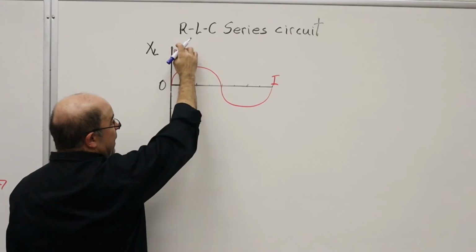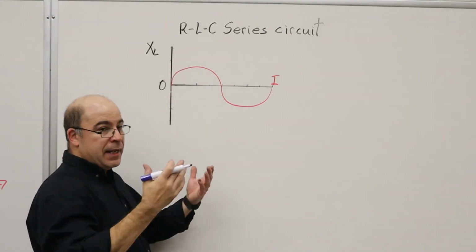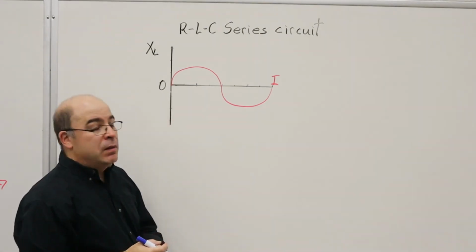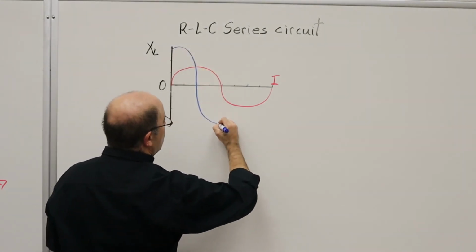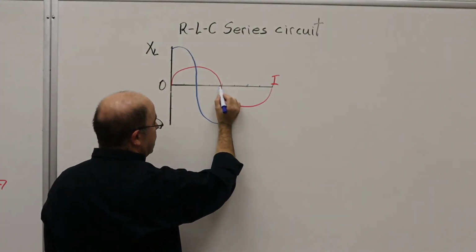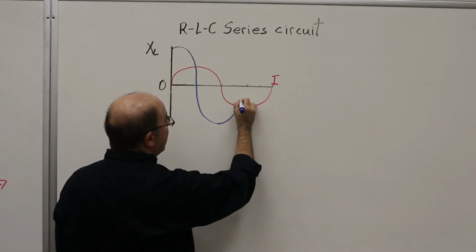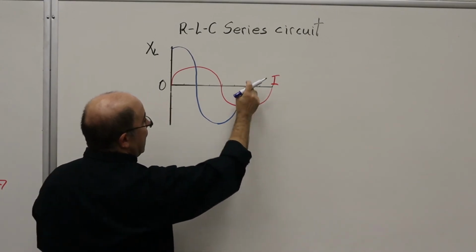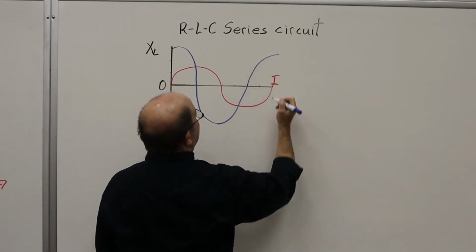Now, I'm exaggerating the amplitude because of the fact we are on film and I want to really capture this. So we're going to start up here. We're going to peak when the current is at a 0 value. Well, that's when the voltage waveform will peak, and then it'll collapse and cross over at 90 degrees of phase angle difference, and continue on the same trend.